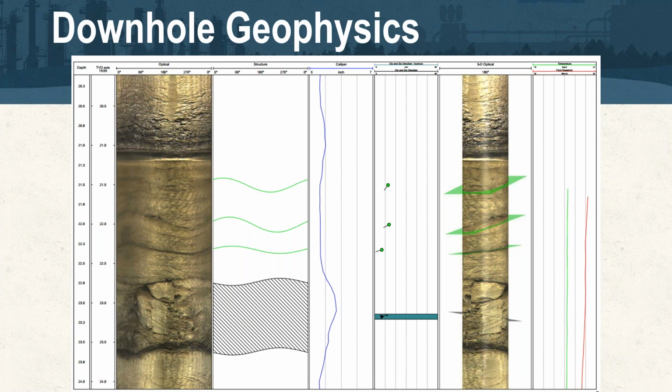Yeah, if there's concerns about borehole integrity and significant potential expensive loss of hardware, we do have a drilling method that we just call pre-drilling. There are other presentations that can highlight this in more detail, or we could share it with the listeners offline, but essentially it involves pre-drilling the hole to the total depth of the remediation and backfilling that borehole with a bentonite seal from the bottom of the hole to a specified depth below grade.